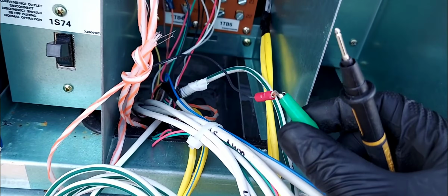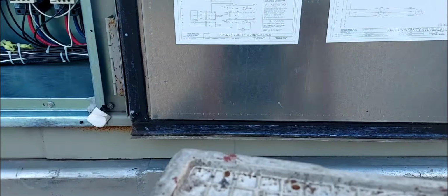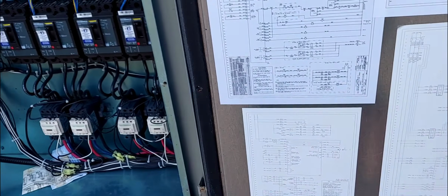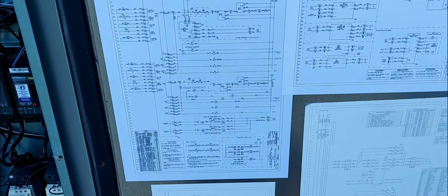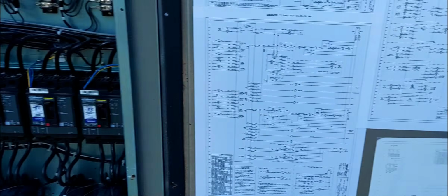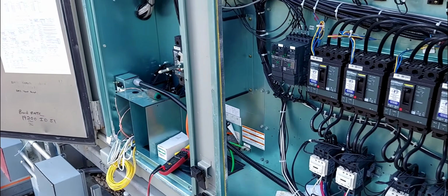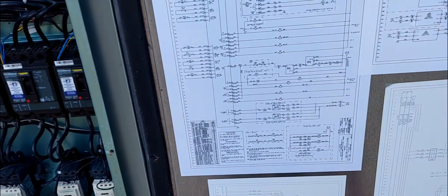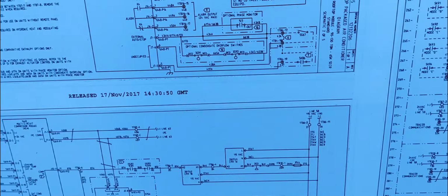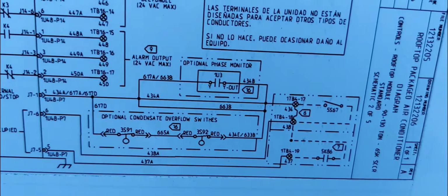So let's put this wire back and then back to the drawing board, schematic, to continue. Now it appears something else is going on, because typically when you have an open switch, you should have potential across it, and there was no potential on 17 and 18. But let's get back to the schematic, and we're going to look at that external stop right here.